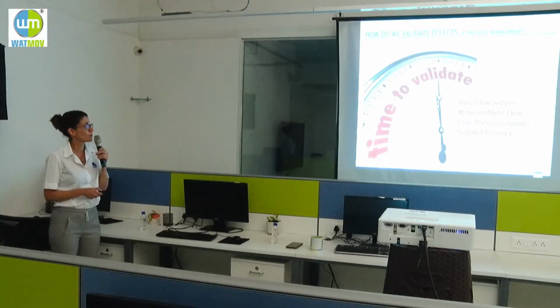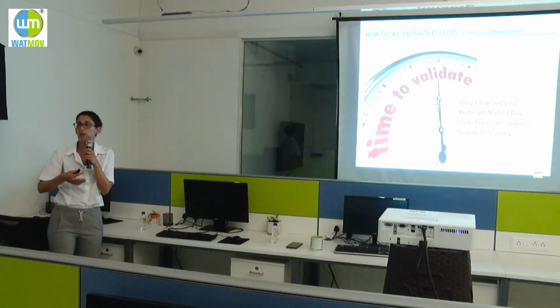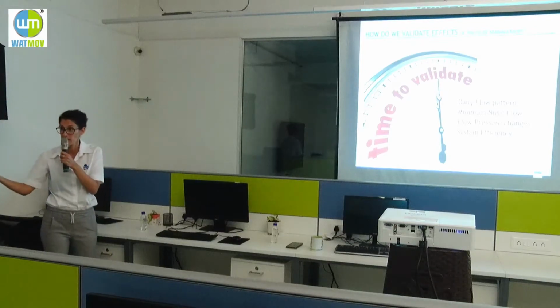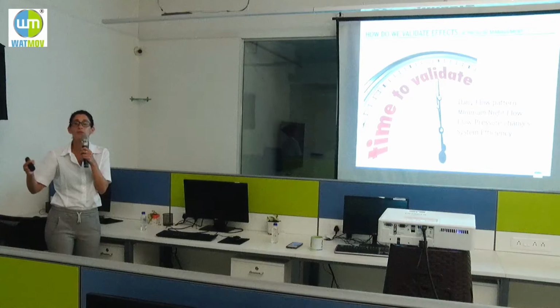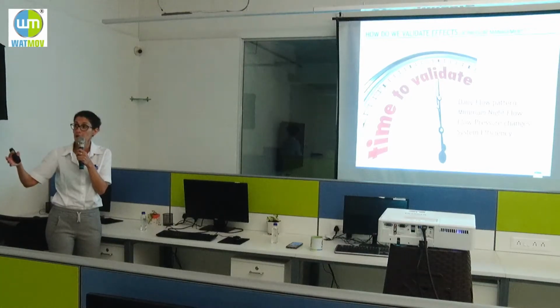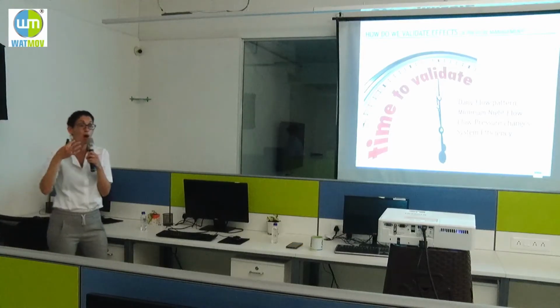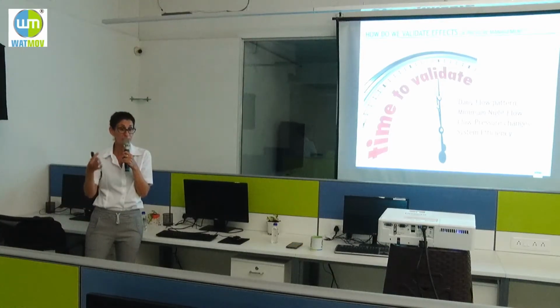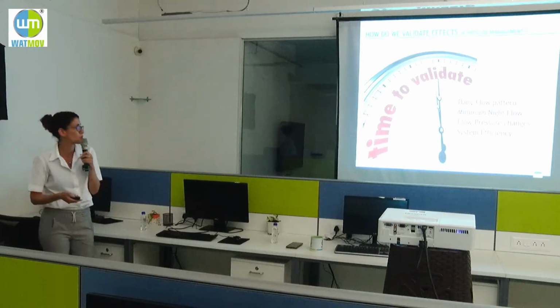Taking into account, we explore the daily flow pattern, because it can vary, for example, between weekends and days of the week, or when we have a special holiday. When we talk about an industrial area, we will see peaks in pressure. So we can explore all this daily flow pattern and analyze it in order to give the most cost-efficient solution.